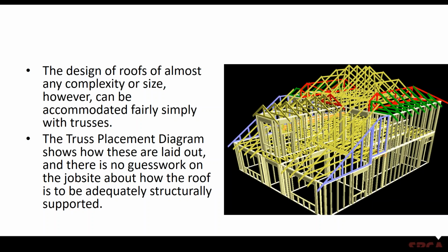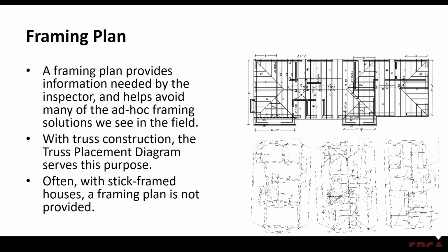There's no guesswork on the job site about the roof. It identifies which trusses go where and where the assumed bearing locations are. Doesn't take the place of a structural framing plan, but it at least provides some additional guidance for those installing the trusses in the field.